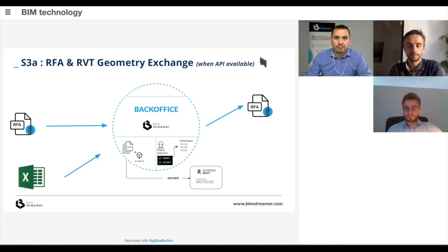Yes, well, those parameters are grayed out by default. It's just a functionality of GSM objects in Archicad, and they are grayed out due to the fact that they are just descriptive parameters. They don't change geometry because they are not.